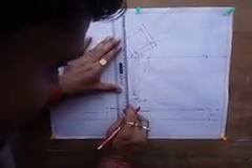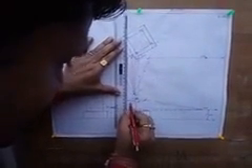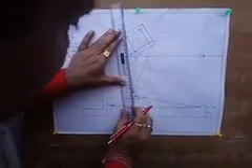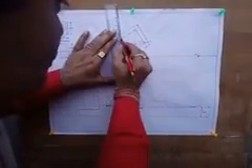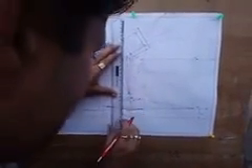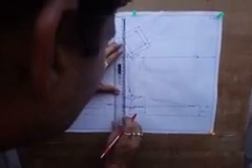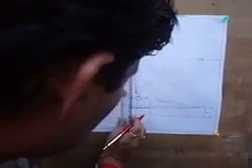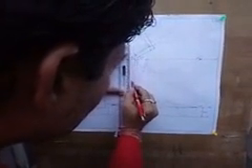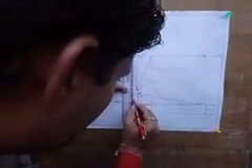We can directly draw a vertical line from 2 to 2 dash, but it is to be confirmed by joining the line 2 dash to the station point, and the intersection on the picture plane is to pass from this 2 and 2 dash. Carrying downward, it should pass through 2 dash. Now I can draw this line.